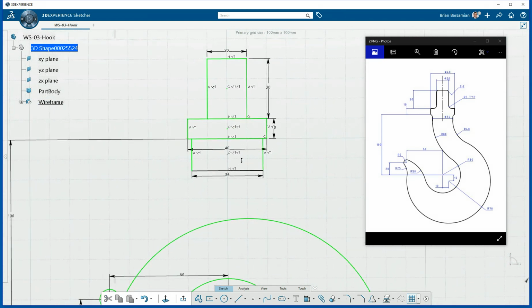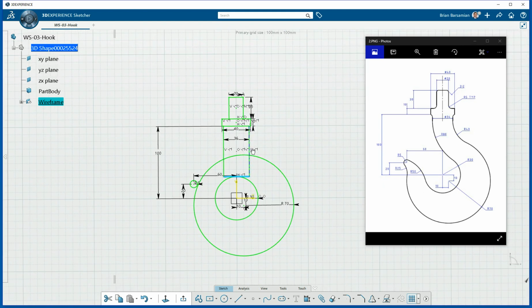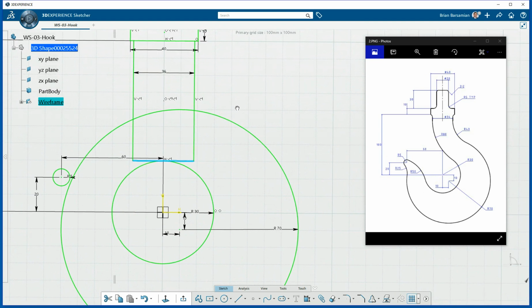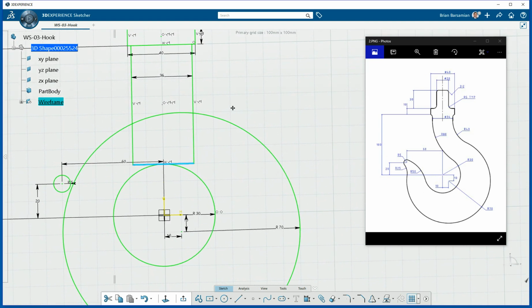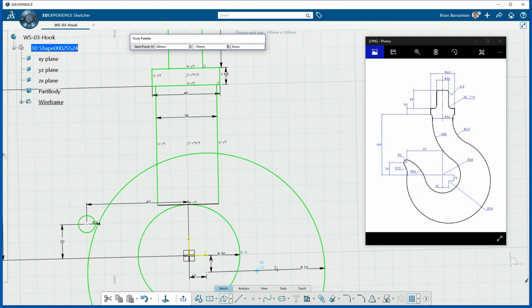What we need this geometry for is to pull it down here. This is going to give us a little area that we can draw this arc in. So now let's start drawing that arc. Now one of the tricks to drawing the arc is, instead of using this 3-point arc command, we're going to actually put these in with the corner command.